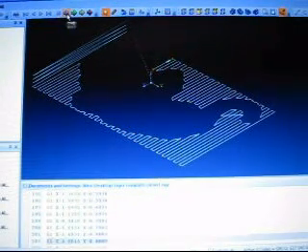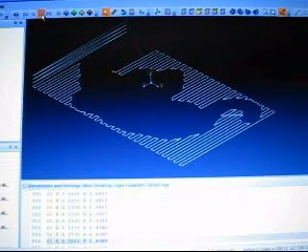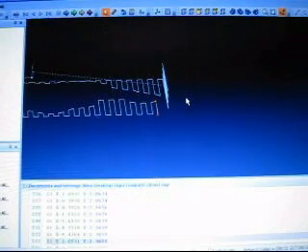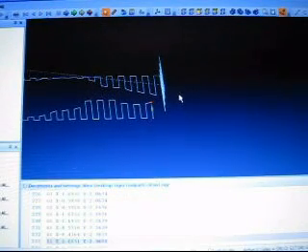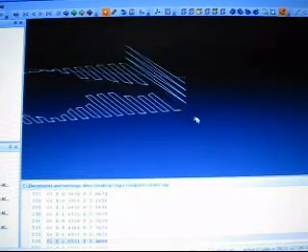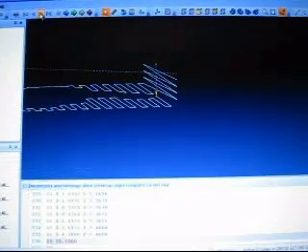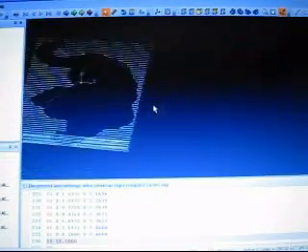And when you get back to over here, as you step closer and closer, now the diameter of this cutter is 1/4 of an inch, okay? So when it gets to this point right here, it's going to come into contact with a little bit extra wood. So what? I mean, the thing is meant to cut, alright, and that's what it's going to do. And then it just rapids up out of the part and then it's done. So that program is done.